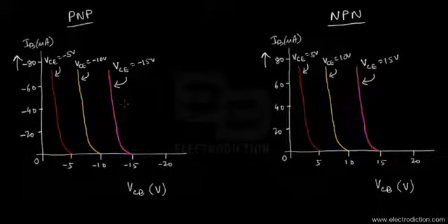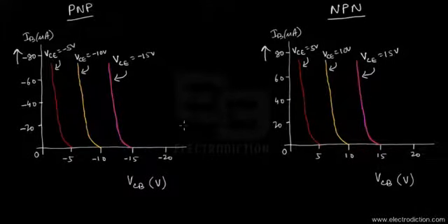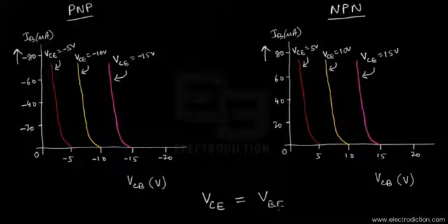If I write down an equation which would facilitate your understanding over here, you'll have already seen from the previous tutorials that for a particular BJT, the total voltage across the collector to emitter terminals is equal to the voltage between the base and emitter terminals plus the voltage drop between the collector to base terminals.